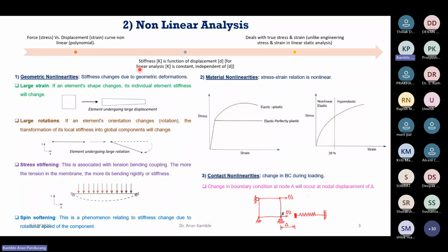Non-linear analysis. Here the force versus displacement, or the stress versus strain curve, is non-linear, or polynomial. And here the steepness is a function of the displacement d. But in the previous slides, for the linear static analysis, the stiffness matrix k is constant, and it is independent of the displacement.